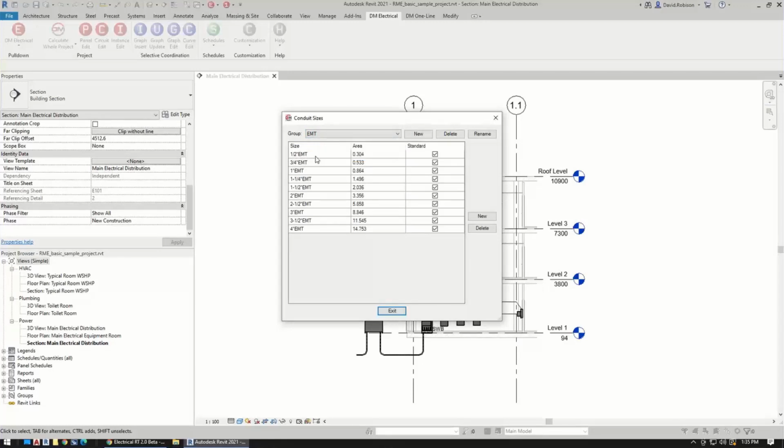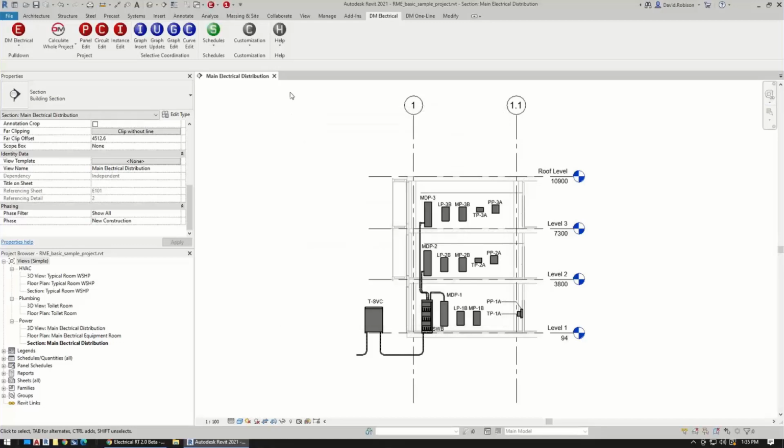And this is just what we've chosen for our default standards to make it clear that this is using EMT conduit or also PVC conduit, so that's differentiated in the wire callout because they have different areas and then different fills. So you do need to differentiate that. It needs to be called out somewhere, and that's how we chose to do it.